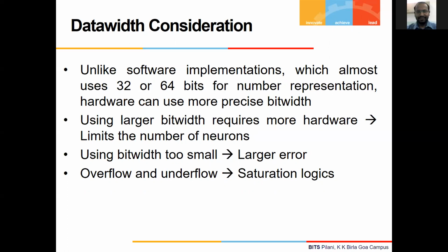Now, looking at those parameters, I can directly find out what is the maximum width I need, which will be log 2 of the maximum parameter value. That's okay? Yeah, that is fine. So from there, I got the maximum parameter value. Another thing that I need to find for bit width is the input: how large the input numbers will be, because I will be multiplying the input with these weights and summing them up.